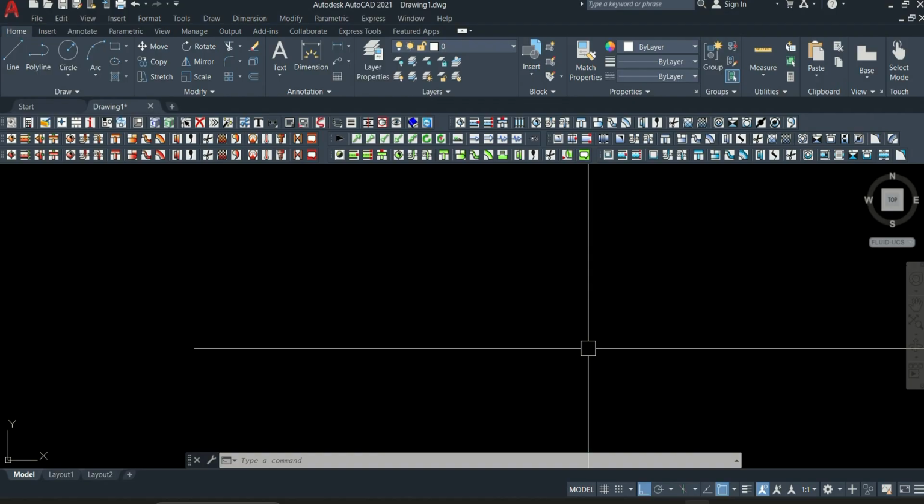before you start any design, any MEP design, one thing you must first of all do is to set your workstation. Set your scale in order for you to know what you are doing on the right scale. Probably you have a drawing you want to work on, that structural, architectural, MEP design. Your scale really matters, so that you know where you're heading to.